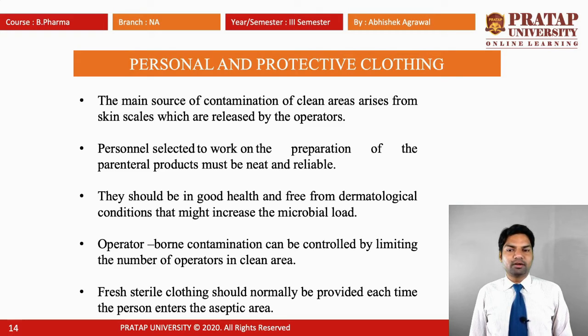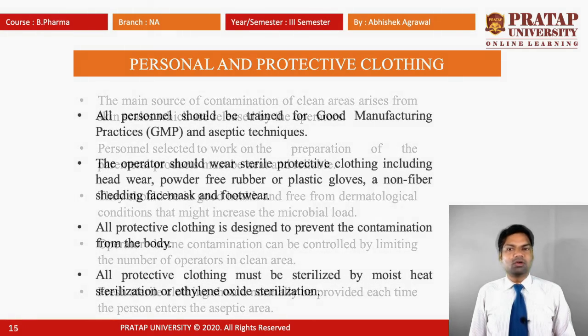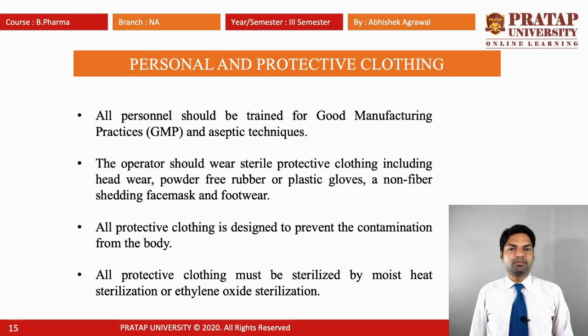So the operator-borne contamination should be controlled by limiting the number of operators in the clean area. Fresh sterile clothing should normally be provided each time the person enters the aseptic area. All personnel should be trained in good manufacturing practice and aseptic technique.